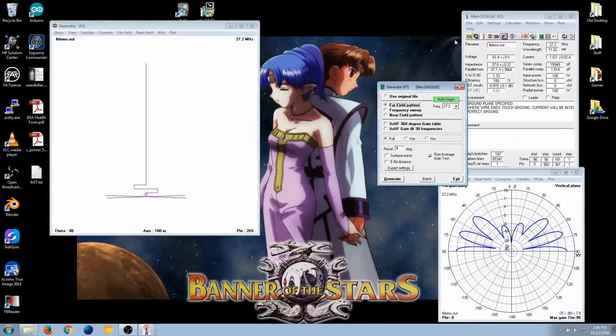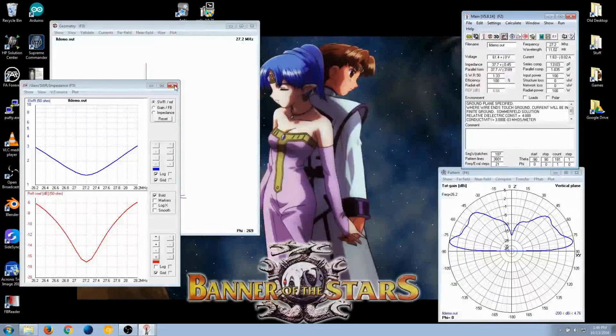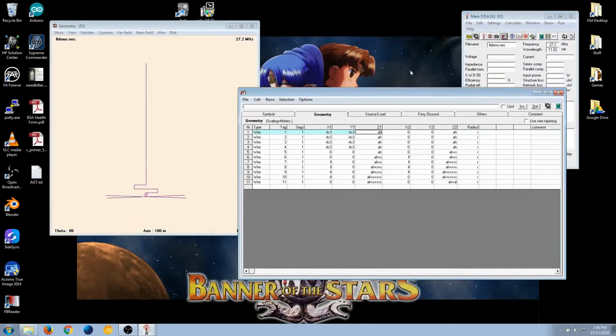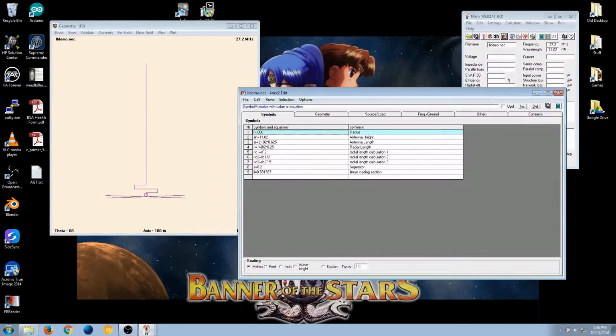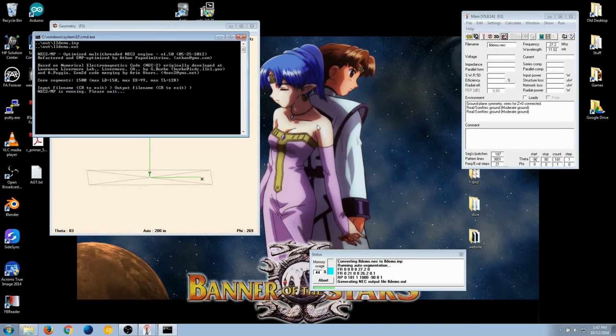That's essentially what I do when it comes to modeling. Really not much more. This type of modeling allows me a lot of adjustments. If I want to make it longer, antenna length, I simply put it here and it modifies the length of the antenna. Say I want to put it at 5 meters above ground. H equals 5. You'll see in here it dropped down. I'm now 5 meters above ground instead of 11.02 meters. That's all the variables do.